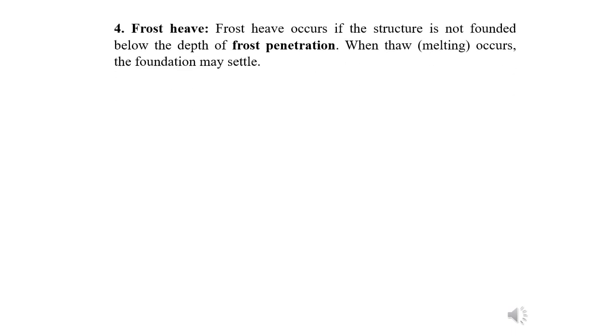Frost heave. From the ground surface up to some depth in cold regions, the soil also becomes ice, right? So if you are not going to find out up to what depth the frost is going to generate, or the ice is going to be formed, then what will happen? There is a chance of settlement. That means we have to construct the foundation below the frost heave.